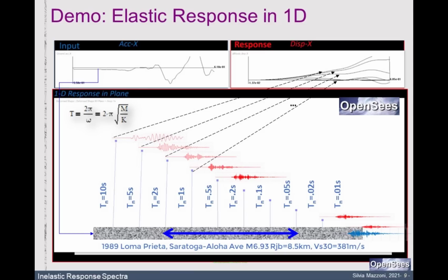You get different maxima, different frequency content, and with the higher frequency ones, the stiffer structures, though not necessarily stiffness because there's also mass associated with it, you almost don't see the deformations, which is an important feature of stiff structures. Just because you don't see the deformations doesn't mean that they're not there, and maybe forces may actually be more important.